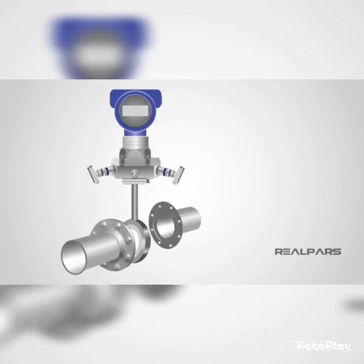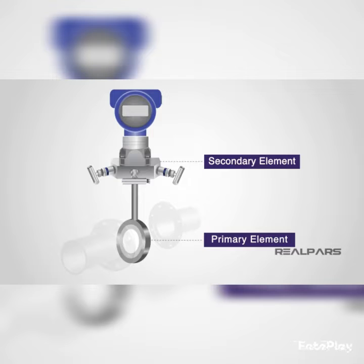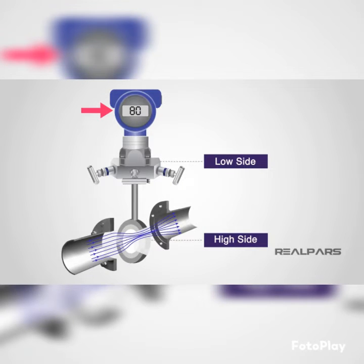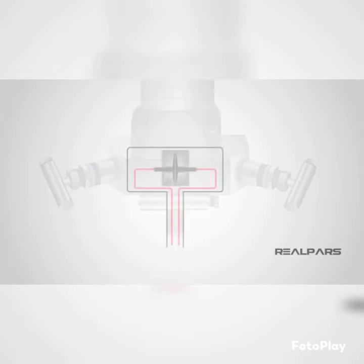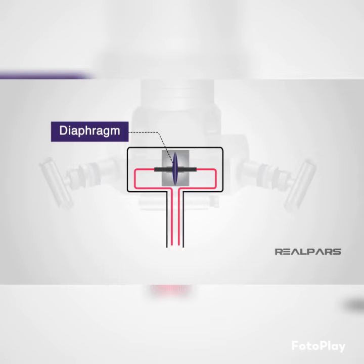The secondary element will measure the difference of pressure produced by the primary element as accurately as possible. The primary element is sometimes called the high side, and the secondary element is called the low side. It is important to remember that the high side and low side aren't always on the respective high and low pressure sides of the pipe. The elements in a dP transmitter will have sealed diaphragms and one of several ways to convert the pressure applied onto the diaphragms into an electrical signal.